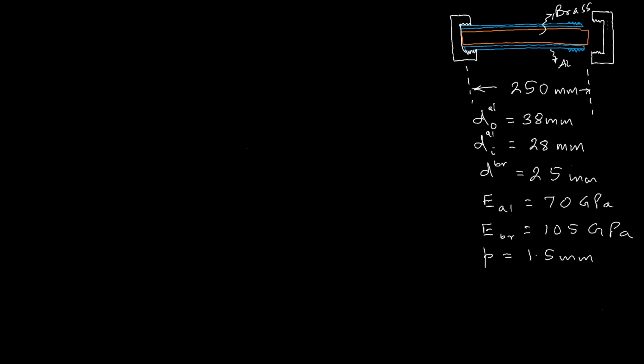Now when we try to plug in the other end cap through this screw thread on the aluminum tube, there will be a gap. This small gap will remain, but if we turn this end cap by a little amount, this gap can be completely closed.